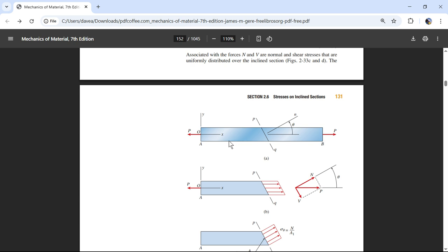And that double-sided tape has two mechanisms for failure still. It can still pull apart in a normal direction, or it can shear across the tape. And this is something where I need to make more tutorials, of just like, let's talk about this, because if you have this double-sided tape sticking these two pieces of wood together at an angle like that, the more tape you have, the more strength in shear that you're going to get.